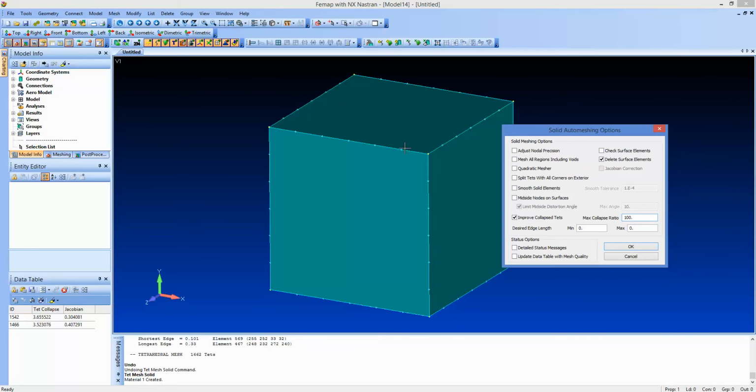The tet we had here, I would regenerate again, but I think it's pretty simple. If you took this corner node and moved it into the cube, so you're flattening that, the more flat that becomes is more of a qualitative thing, but the more flat that tet becomes, the higher this ratio becomes, okay? Like 10 to 1 is pretty bad. So if I was going to run this, I'd set this to 10 or something else rather than 100 and say improve it.